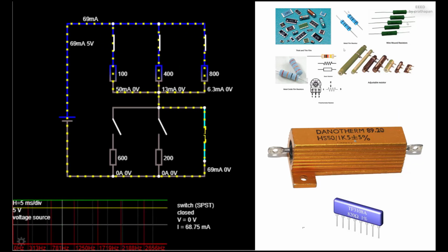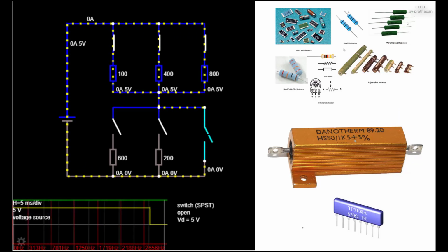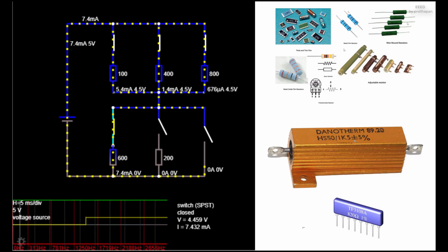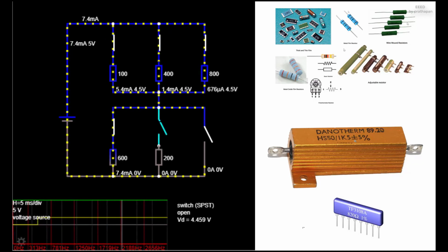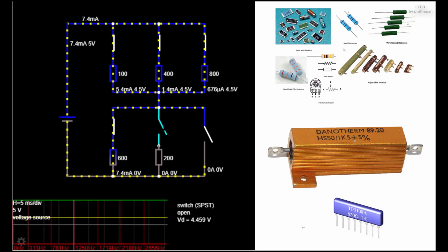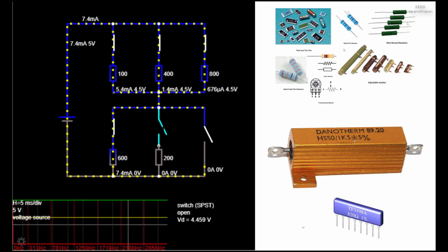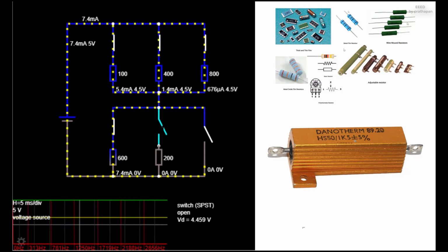If there is only one switch closed on top and one closed on the bottom, then there is a single path through the circuit, and by Ohm's law, the current will be equal to 5V divided by the total resistance through the current path. If there are multiple current paths, you may have resistors in parallel.